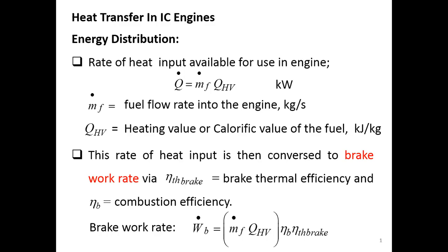Okay, so let's first look at the energy distributions, right? The input comes from the heat. The amount of heat that is available for use in the engine comes from the mass flow rate of the fuel times the heating value, or the calorific value, of the fuel. So this is the amount of the input heat, and this amount of heat will be distributed throughout the internal